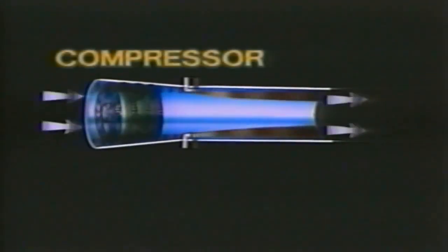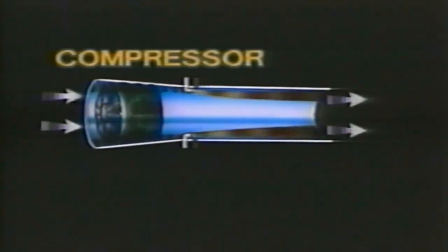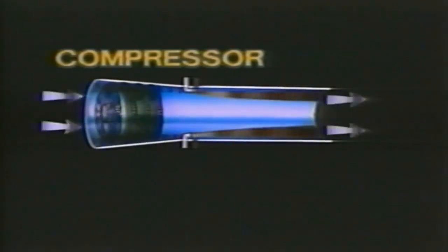Now, put in a second, third, and fourth stage. Bolt them all together so they'll rotate as one unit, and we have a four-stage compressor. Rotating at high speed, it draws air in from the front and compresses it. Stage by stage, it forces the air to flow into a progressively confined space until finally it delivers high-pressure air